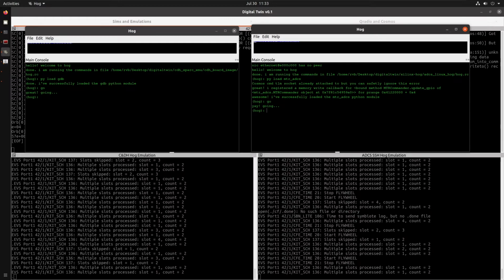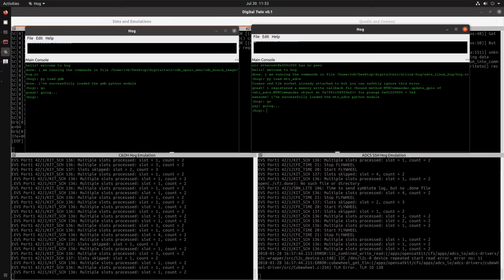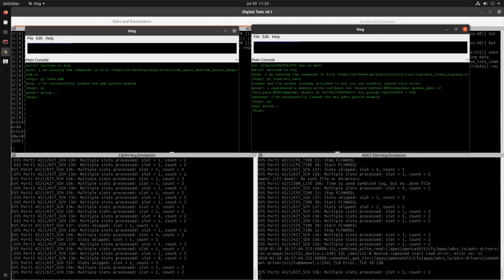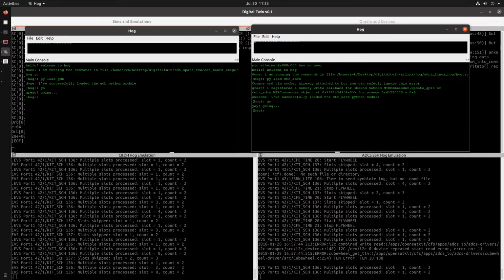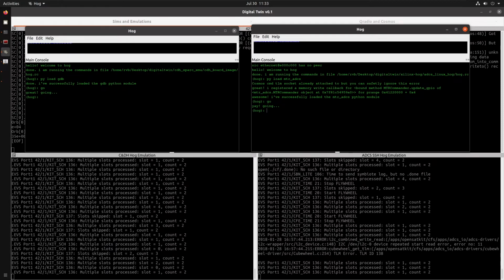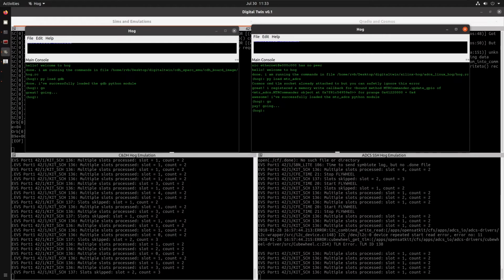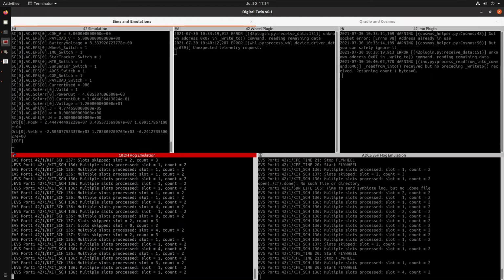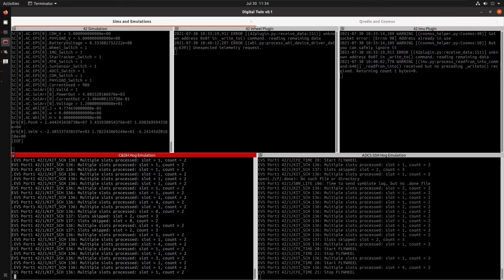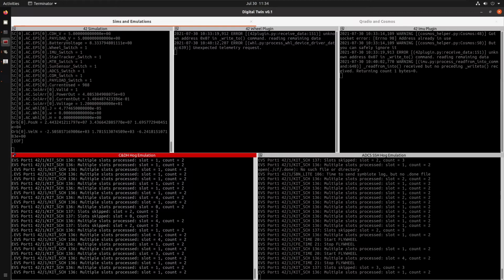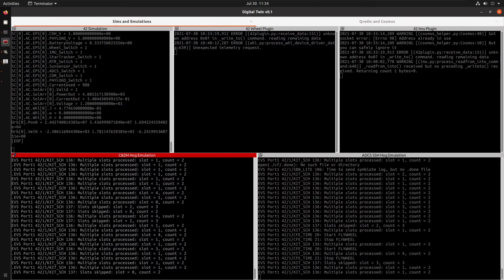For the digital twin, we use this plugin system to provide simulated truth data to the emulations through the various protocols that the ADCS and CNDH firmwares are expecting. This means that there is no custom firmware built for use only on the digital twin. Any firmware that can be flashed on the actual hardware can be loaded into the digital twin with no modifications. So in short, we have flight firmware running in emulated hardware thinking it's in space. You can command it like it's a real satellite and it behaves almost identical to its real-world counterpart.